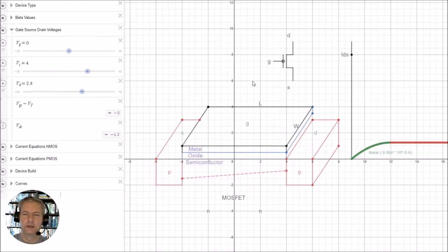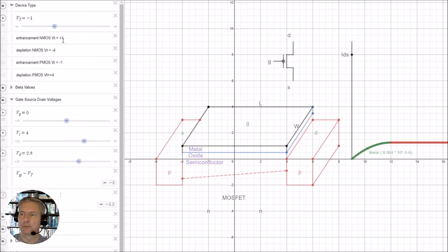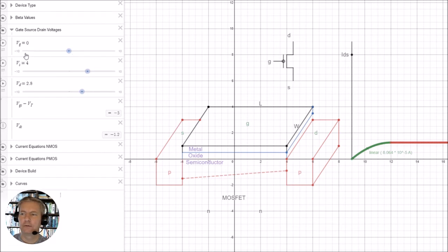In terms of its switching, you see that this device operates in the opposite sense from our Enhancement NMOS. So this is now the Enhancement PMOS. In the Enhancement PMOS, whenever the gate voltage is sitting at 0 volts, the device is going to be on. But whenever the gate voltage rises up to 5 volts, the inversion region is getting smaller, until the gate voltage gets to the value where VGS minus VT becomes 0, and we then have the device cut off. So if we're up at 5 volts, the device is hard off. That is, it's not drawing any current.